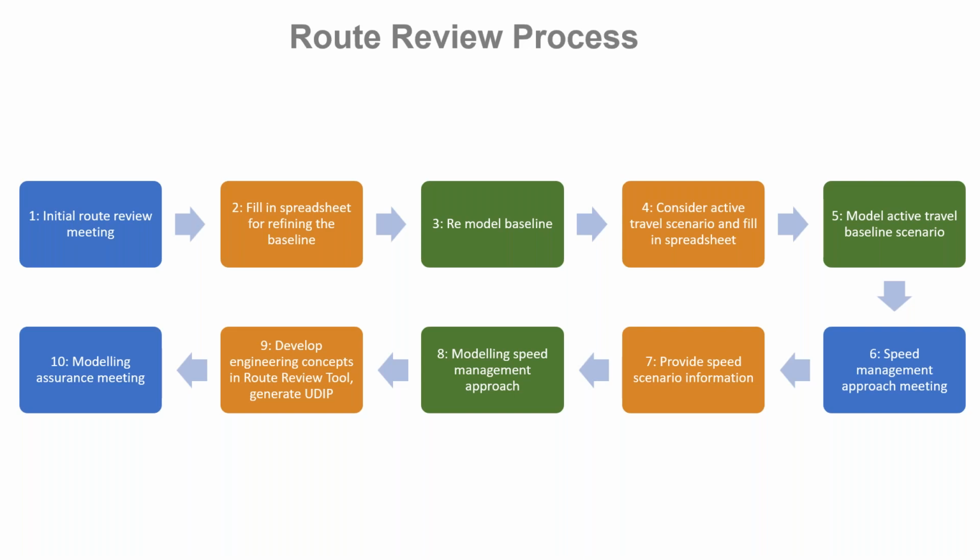So we start here with an initial meeting with the road authority staff, just to take a step back and really understand how the road's performing. And we do that by looking at the fatal and serious injury worms, the FSI profile in the route review tool, and the overall star ratings. We look at the component parts of risk, we look at what's in the Safer Roads investment plan, because it can give us a clue about which direction to go in.